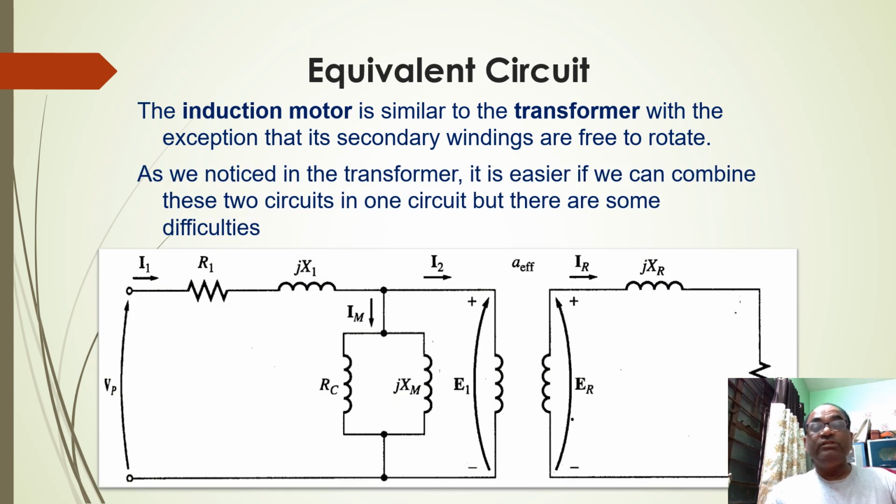As we had talked in the previous video, an induction motor can be assumed to be a transformer with a secondary shorted electrically. So the induction motor's equivalent diagram can also be shown like a transformer. As the primary and secondary windings of the transformer have resistance and reactances, here also the stator and the rotor windings have resistance and reactances.